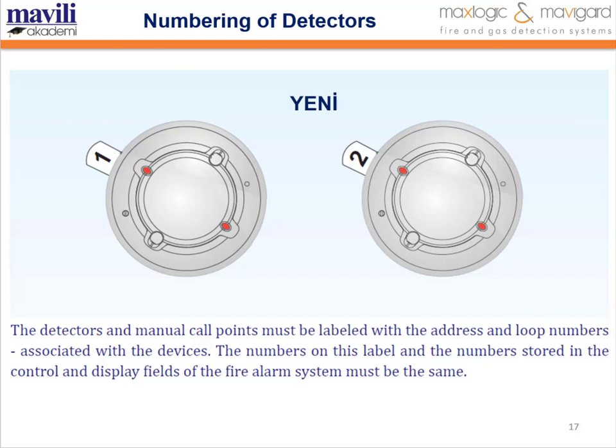If detector tags are used to provide the necessary cross-relationship between detectors, alarm buttons, and control and indicating equipment, identification numbers or letters must be added to detectors and call points that reproduce the indications provided on the controller.